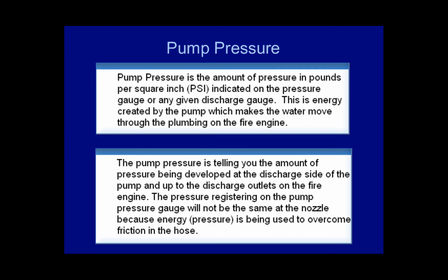The pressure registering on the pump pressure gauge will not be the same at the nozzle because energy or pressure is being used to overcome friction in the hose.